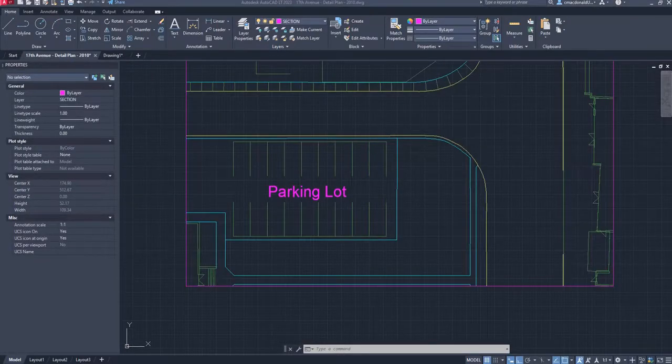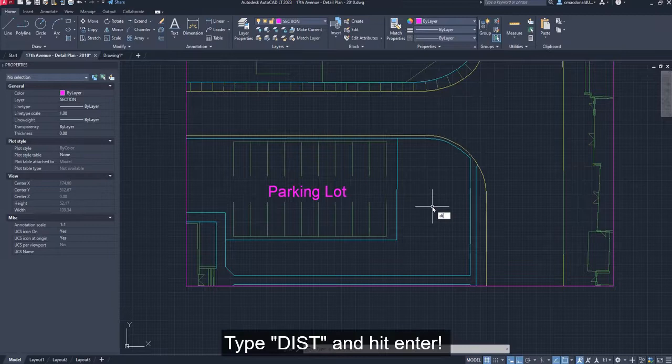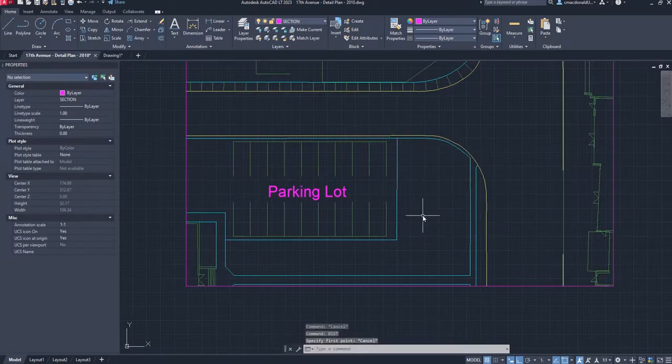Now there's a final quick tool for your tool bag in AutoCAD that will be handy when you're doing quick on-the-fly measuring of things that might be useful to collect measurements for. That is the distance command. Distance, or DIST, will allow us to pick 2 points, and it will produce an exact measurement of the distance between those 2 points. Let's escape. Let's try it once. DIST. We'll hit enter, and now we can measure the distance.